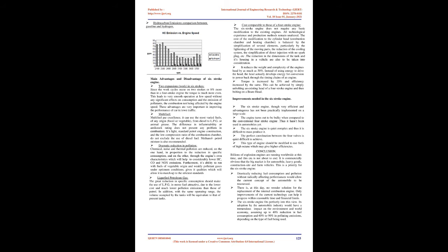1. Intake valve, 2. Heating chamber valve, 3. Combustion chamber valve, 4. Exhaust valve, 5. Cylinder, 6. Combustion chamber, 7. Air heating chamber, 8. Wall of combustion chamber, 9. Fuel injector, 10. Heating plug, 11. Piston, 12. Crankshaft. First stroke, the inlet valve, 1, is kept open.